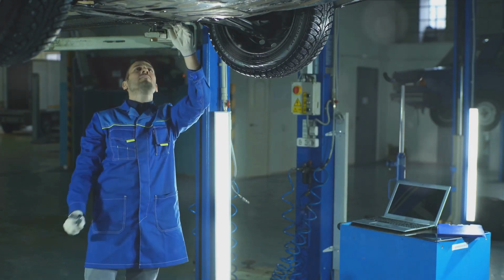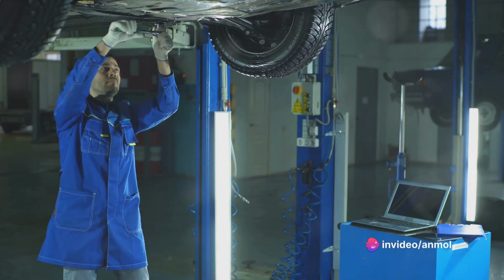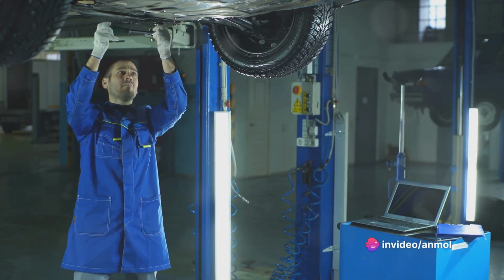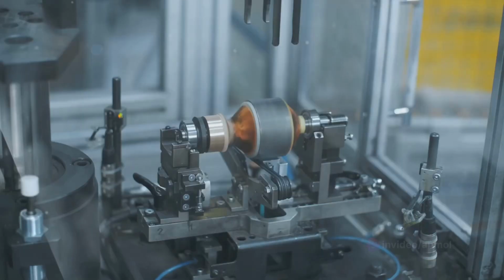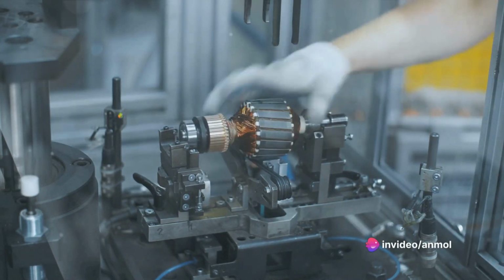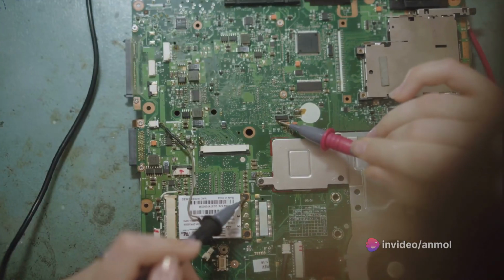Lastly, we turn our attention to the motor behavior. Is it running hotter than usual? Is it vibrating excessively? Or perhaps it's not running at all? Observing the motor's behavior can offer us insights into the internal workings of the VFD. For instance, a motor running too hot might indicate that the VFD is supplying too much voltage, while a motor not running might suggest a problem with the power supply.